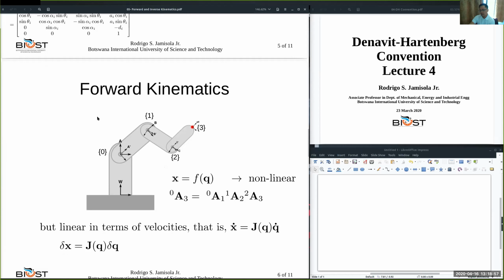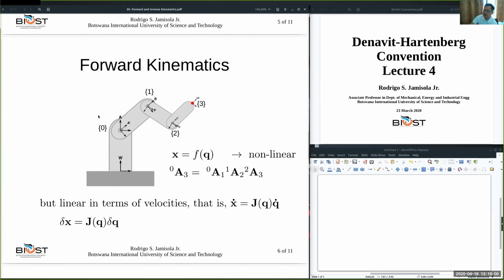Okay? And so, for example, when we are doing the forward kinematics of a manipulator, in this example, it has 3 rotary joints. And in this case, it's a planar robot. Again, still a planar robot, but with more joints, I think this is the Puma or similar to a Puma. But if you add more joints, then the geometric solution won't be enough. So we need to define how to attach the reference frames and define the Denavit-Hartenberg parameters and compute the transformation matrices.